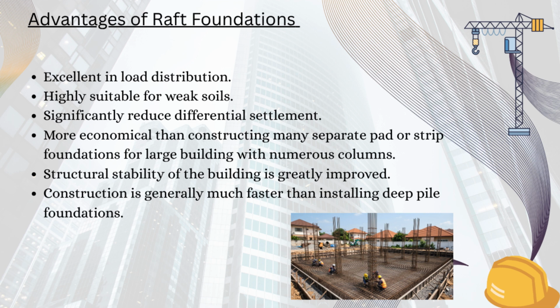For large buildings requiring numerous footings, a raft foundation can actually become more economical than constructing many separate pad or strip foundations. In many cases, it can even eliminate the need for much more expensive pile foundations. Because all columns are connected by one reinforced concrete slab, the overall structural stability of the building is greatly improved.